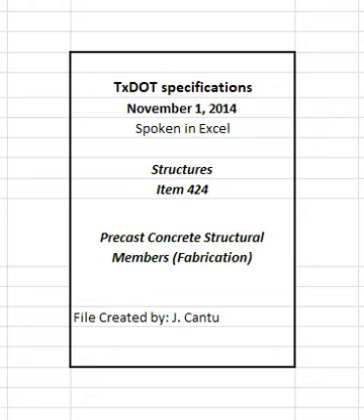Withdraw the vibrators slowly to avoid forming holes after the concrete is thoroughly consolidated. Do not allow prolonged contact of vibrators with forms so vibrator marks on concrete surfaces are minimal. Do not use vibrators to move concrete to other locations in the forms. Use vibrators with non-metallic vibrating heads to prevent damage to the epoxy coating when epoxy-coated reinforcing steel is used. Increase the consolidation time and decrease the insertion spacing, if necessary, when using these vibrators.